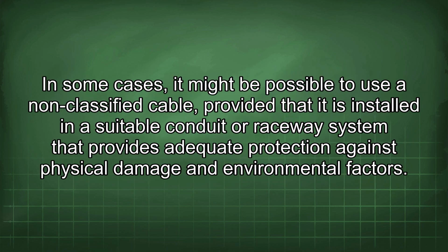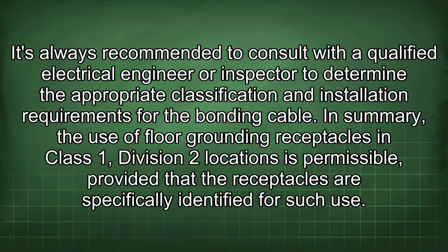In some cases, it might be possible to use a non-classified cable, provided that it is installed in a suitable conduit or raceway system that provides adequate protection against physical damage and environmental factors. It's always recommended to consult with a qualified electrical engineer or inspector to determine the appropriate classification and installation requirements